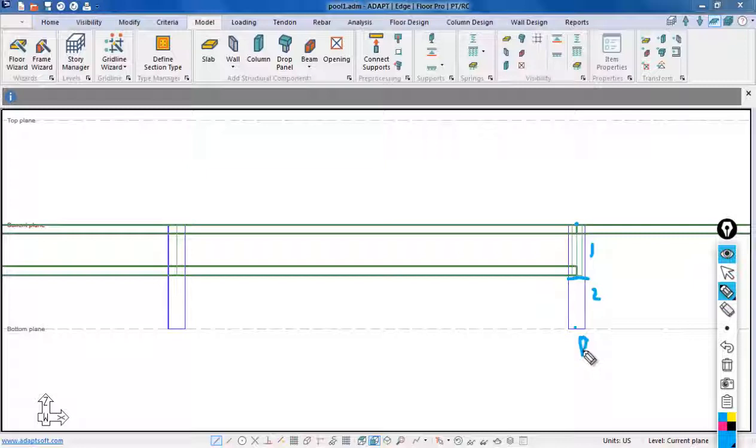This would be the bottom reference plane, which is called bottom plane, and the top reference plane of the column is shown here, top. So if the node, and I'll put the node in pink, if the node of the column is below the reference node or the physical node of the beam, in this case it's obviously below, this is acceptable.